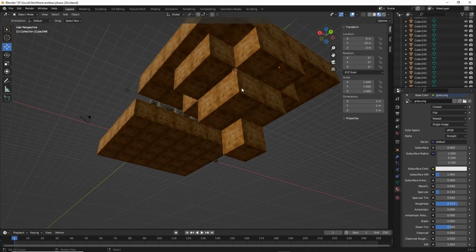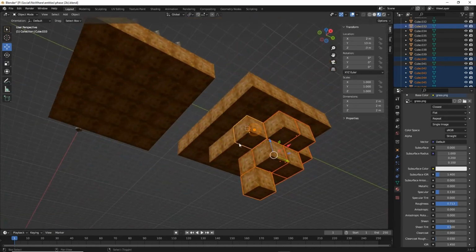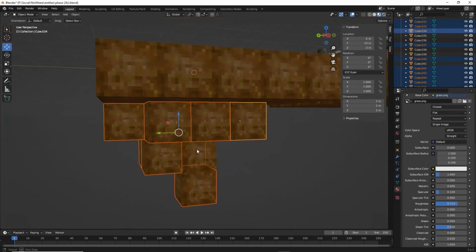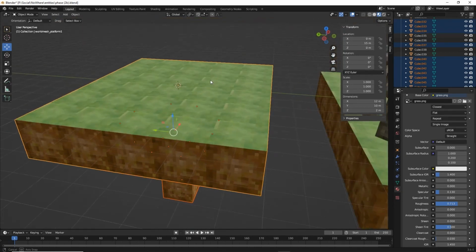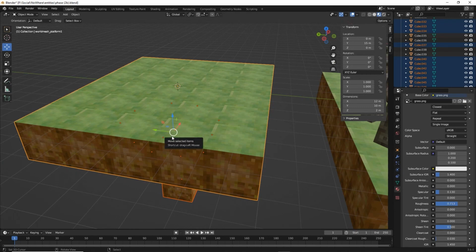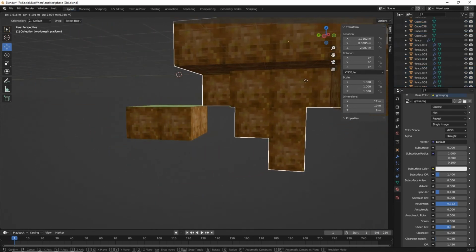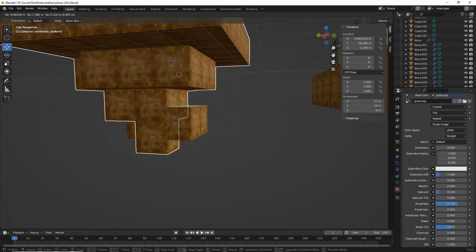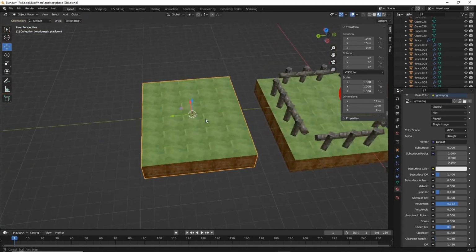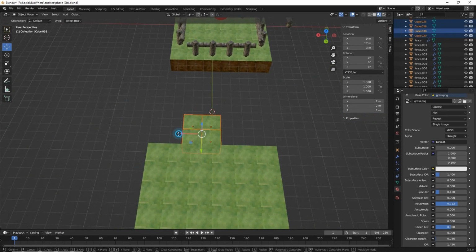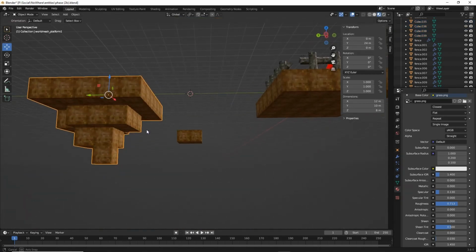So we're giving the platform a little bit more depth. So let's select all of these, and join that to our mesh. So shift click, platform shift click last, object, join, and there's probably a couple in the middle that we don't really need. Let's just move this out of the way for the moment. We can reuse these, so just move them to one side. So this is platform 1.